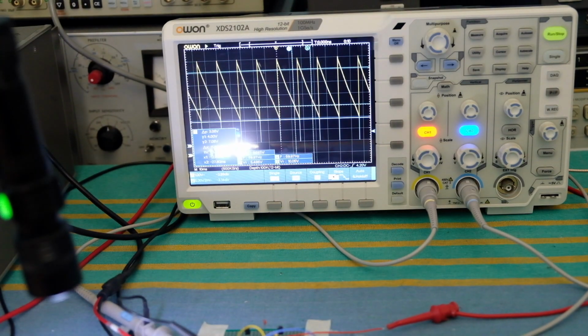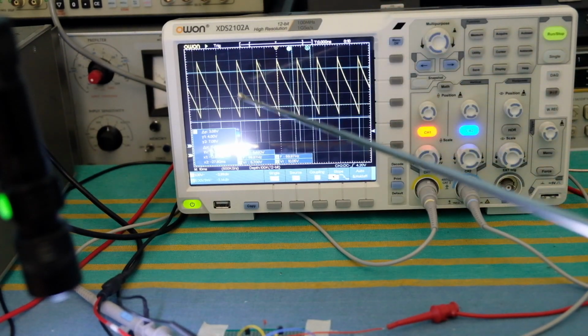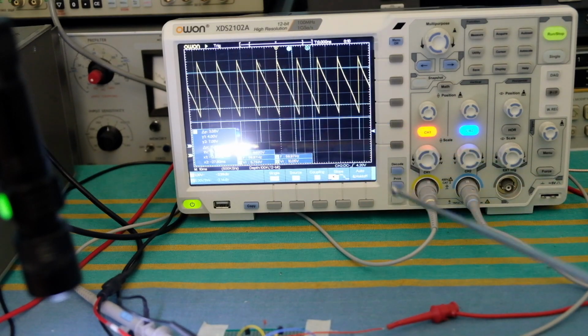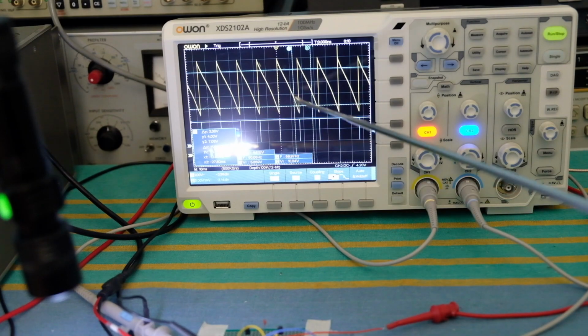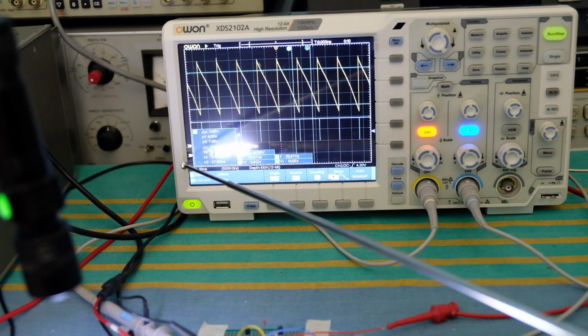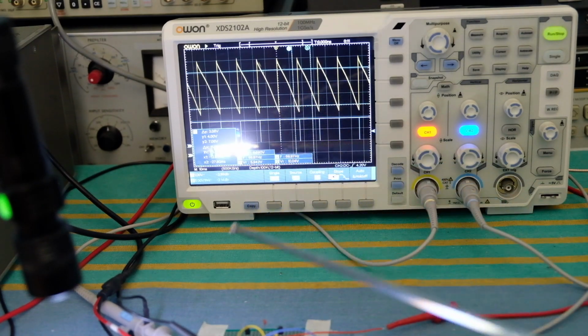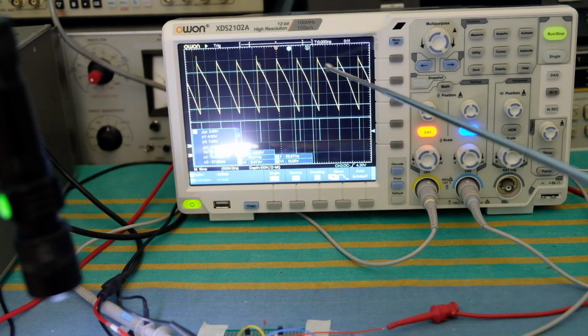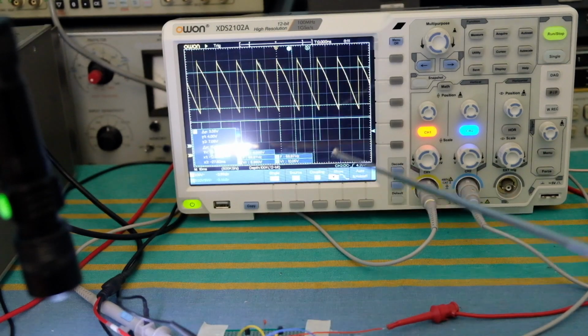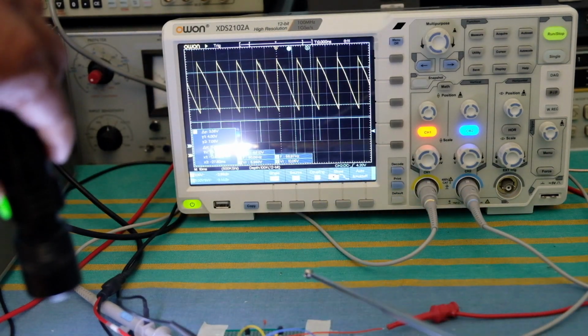So with a 330 picofarad capacitor, you can see a very large voltage drop, on the order of 5 volts or so, as I mentioned. And so it's possible that it's not quite reached the ground level, which is over here. That means this is operating in a fairly good operating region for us to be able to measure this without any distortion on the source follower itself.